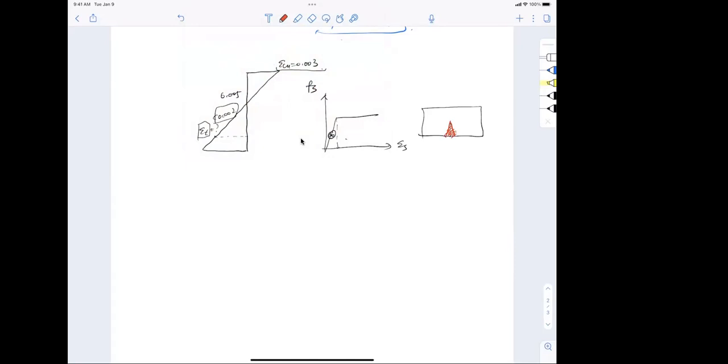And so in the transition zone, you'll see some crack before failure, but not so severe. If it's over reinforced, you don't see a whole lot of crack at all. It just goes from looking nice, and the next moment the concrete crashes, kapoof, everything's gone. You don't have time to run. I'm sorry to jump in here, this is also my question. Okay, good.